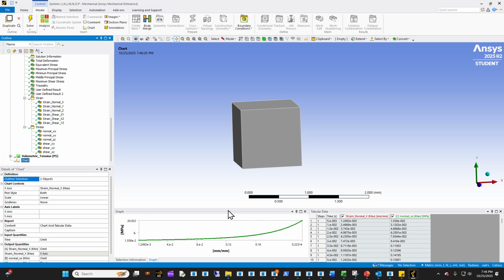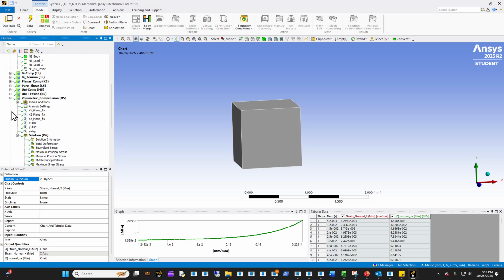And that's basically how you can verify, depending on how the hyperelastic curve is generated, because hyperelastic curves are generated based on some combination of these tests, right? So they might have a biaxial tension, biaxial compression, they might have volumetric compression. However the test is being used to generate the material model, you can use that specific stress state to verify that the material model is correctly implemented by comparing that to the test results. And that's how you can use a single element study.